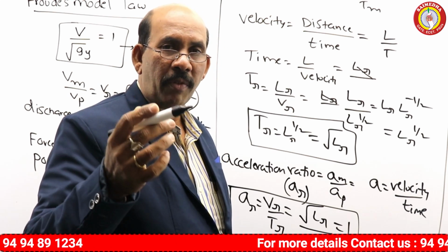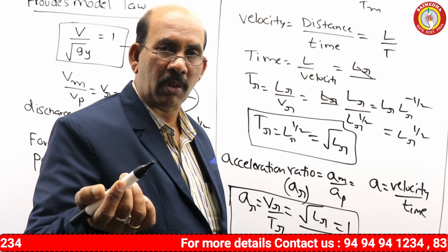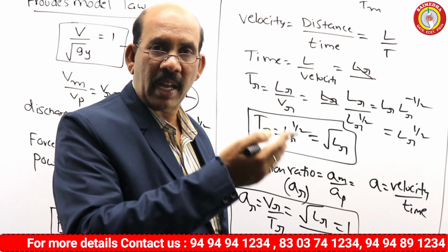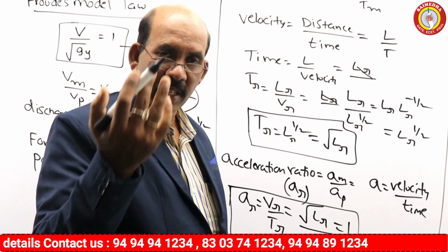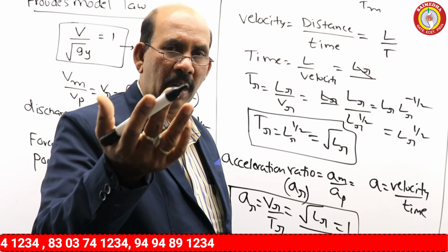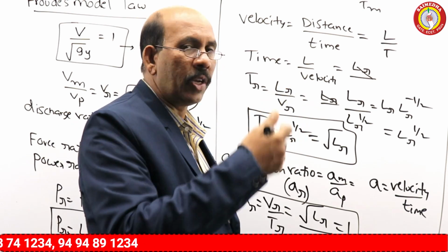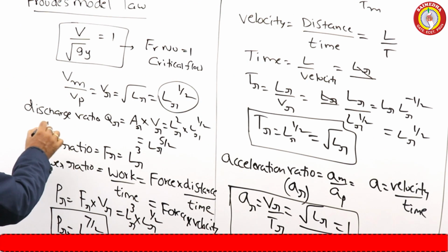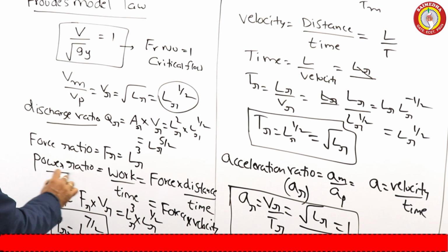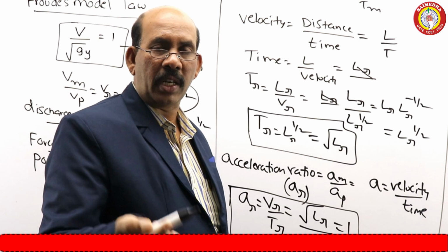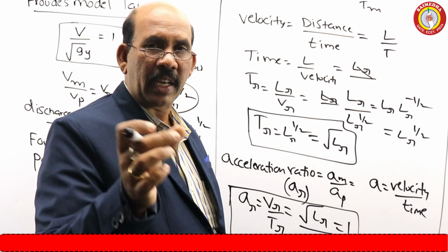the various quantities in reality, either in the model or in the prototype. As I told, there are various applications of these models, especially open channel flow, and the discharge over a spillway is the best example to analyze this Froude's model. Now, especially the discharge, the power and the force are very commonly used in our civil engineering examples.